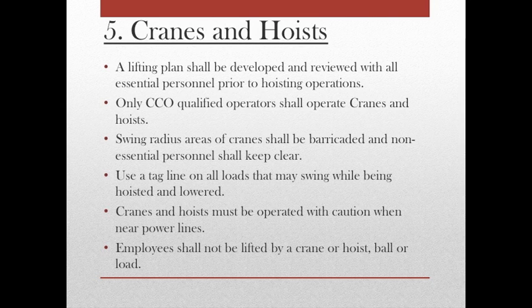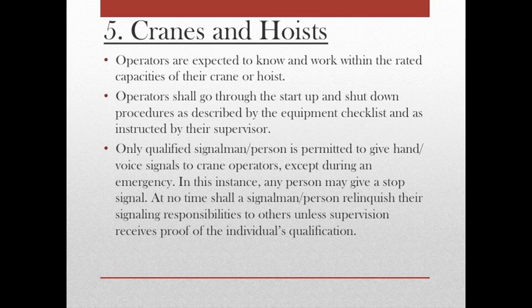Employees shall not be lifted by a crane or hoist ball. Operators are expected to know and work within the rated capacities of their crane or hoist. Operators shall go through the startup and shutdown procedures as described by the equipment checklist and as instructed by their supervisor. Only a qualified signalman is permitted to give hand and voice signals to crane operators, except during an emergency. In this instance, any person may give a stop signal. At no time shall a signalman relinquish their signalman responsibilities to others unless supervision receives proof of the individual's